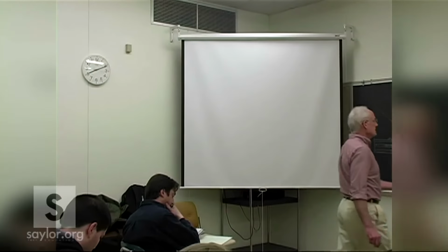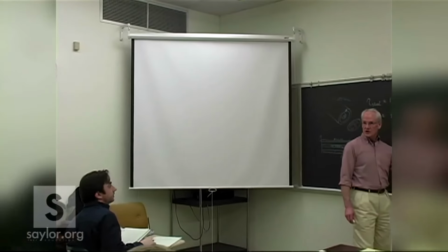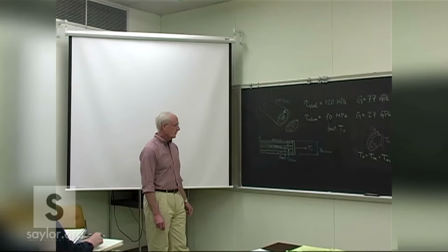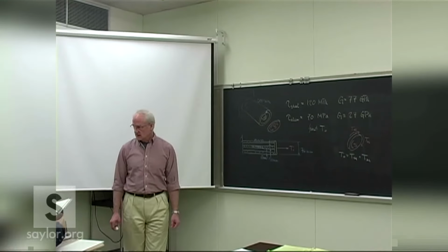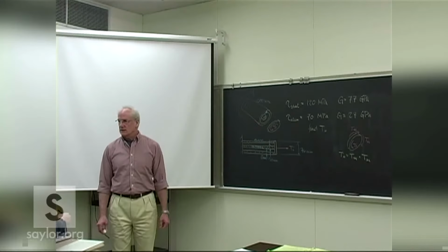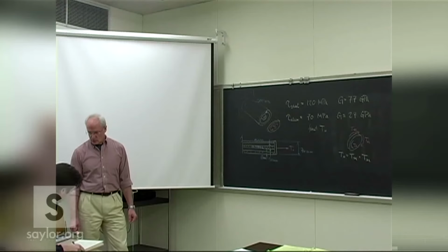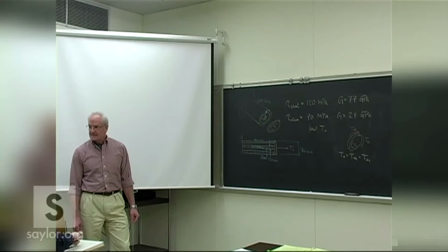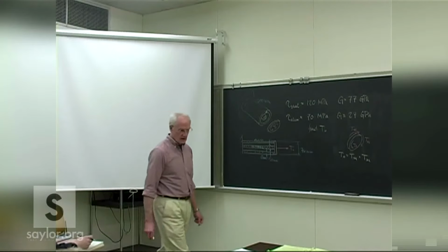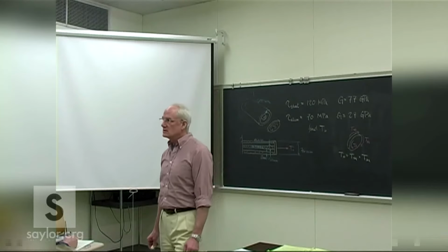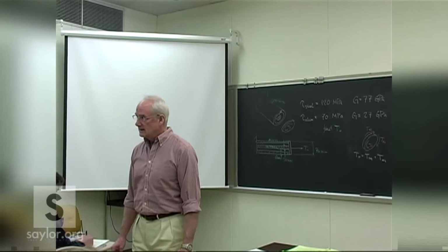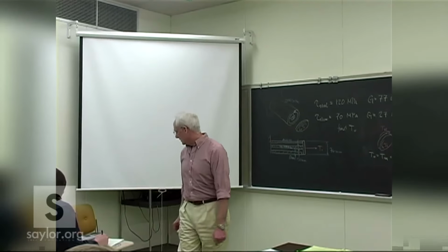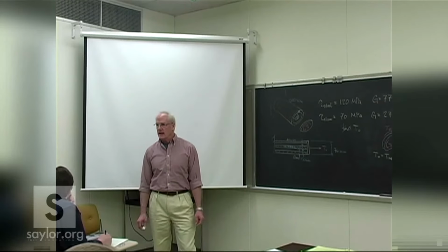We have two unknowns. How much torsion goes into each? Actually, this is three unknowns, I guess, since we don't know any one of those. We just know that the applied torques to the individual members has got to equal the total torque applied to the entire thing. So what other things can we bring to our aid from this term? We're looking at deformation, so it's going to have to be something of that.